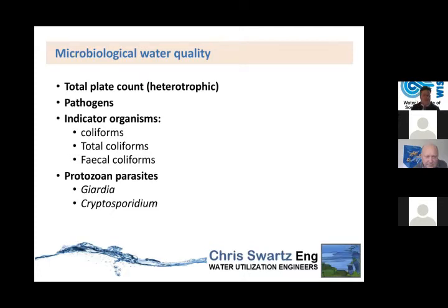And these can be either bacterial in origin, it can be viruses, it can be parasites, typically Giardia, Cryptosporidium, and it can be waterborne, water carried. There's lots of routes that it can get into the water and that it can cause a health risk. This is mostly acute, so if you drink water with high amounts of pathogens in, you'll become very ill, and if you don't see a doctor and get rehydrated, then you can also die. Typically, cholera is a good example, cholera outbreaks that we've had in the country.